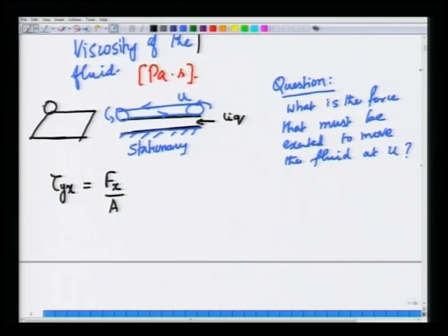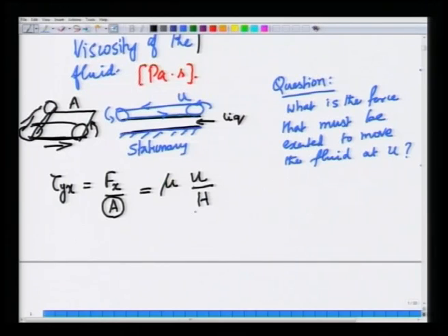This whole sheet is a cylindrical roll in the third direction, and this whole roll is rotating at a constant velocity, and the area of the top plate, or the belt surface, is A. So, that is the area. This is the viscosity of the fluid times u divided by the gap thickness. So, force is therefore mu A u divided by h.